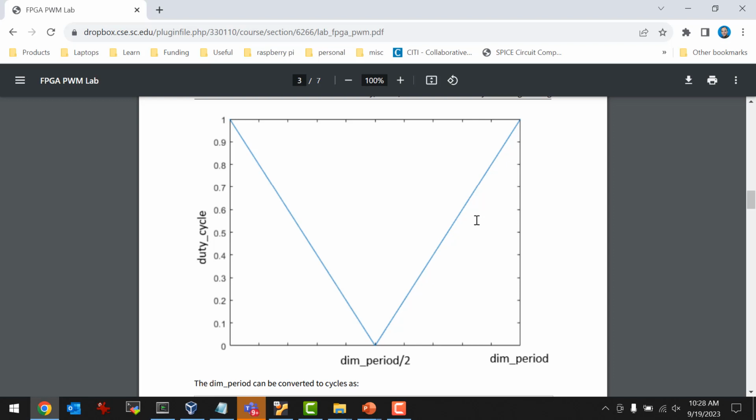Tens to hundreds of microseconds, which is a pretty short period of time even for a computer, right? That's why, by the way, PWM is typically not bit banged. We want to do it in this lab just to have the experience of having done it. But even on Arduino, there's usually specialized hardware. Intel doesn't know this apparently, but there's specialized hardware for PWM because PWM is a very short time scale.